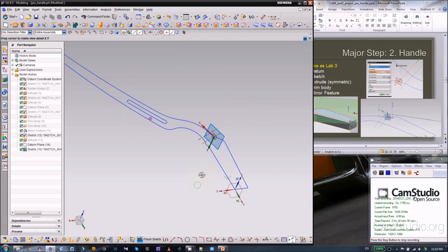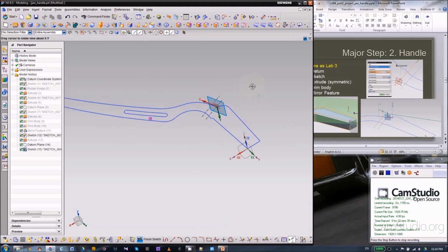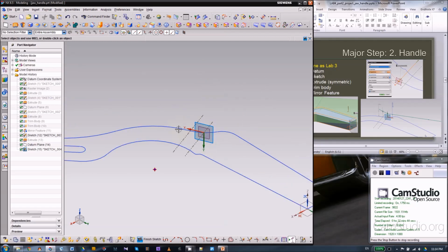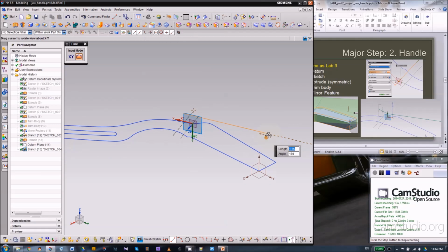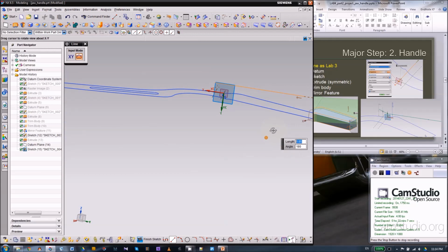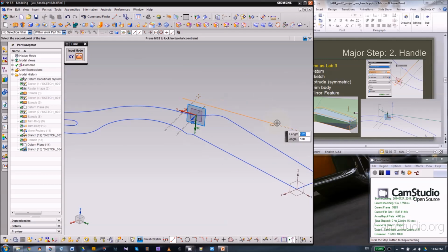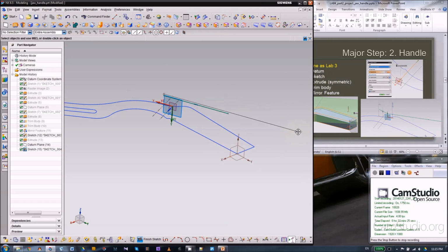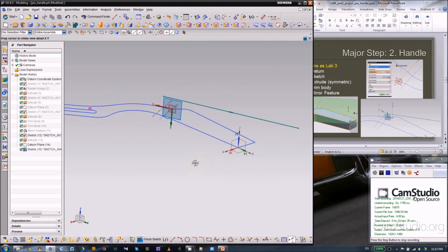Okay, we want to make the side with the slot thicker, and the side that goes to the jaw thinner, so that's about this position. And I did flip the coordinate system, which is different from what we have in the slide, but anyway, we know where this line goes. That's enough. So first will be a horizontal line. Although this is not horizontal now, if you look at the sketch orientation, you can see it's horizontal. And since this is pretty well 3D, I'd like to draw this sketch in the 3D view. Also you want to make sure this line is actually a lot longer than this piece. So if you look at it this way, you want this line to be able to cut into the solid.